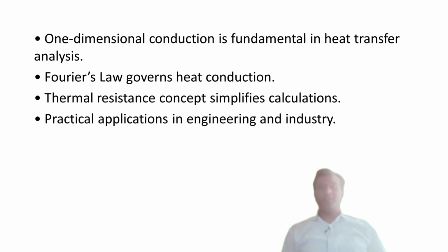The thermal resistance concept, R equals L by KA for a plane wall, or R cylinder equals ln of R2 by R1 divided by 2 pi L k for cylinders, simplifies our calculations, making it easier to predict and optimize heat transfer.